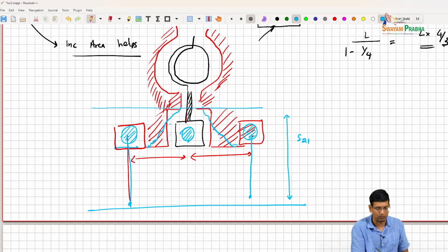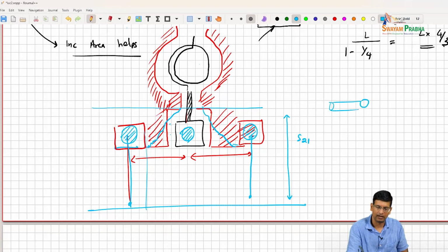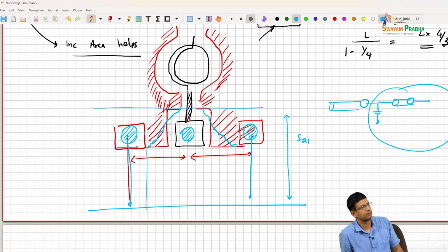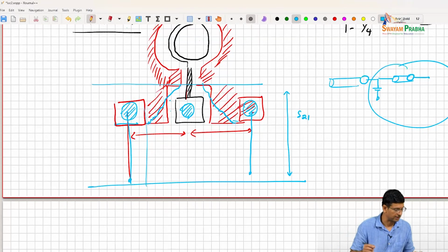You have to take your ground plane, put that, model the bumps, and then on your PCB you have a ground plane. You have to model that whole thing and model the transition. And usually it depends upon the bump size, but it can end up looking like a capacitance discontinuity. So you have basically a 50 ohm line and then a capacitance and then maybe something that loads 50 ohm. So now you have to design your network to accommodate this. So coming back to the inductor itself,